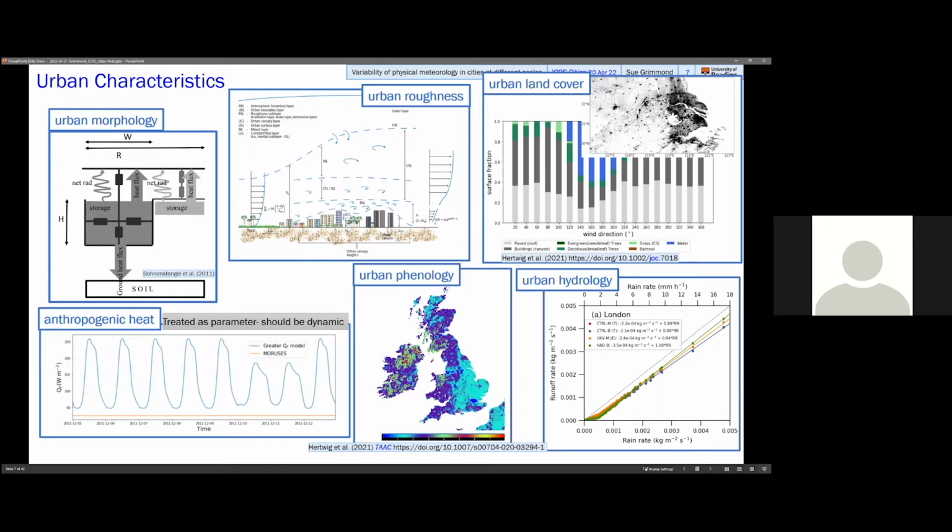We also need to account for the roughness of urban areas. This may be represented by drag coefficients and/or roughness lengths and zero plane displacement heights. These typically assume that the buildings are all of the same height and use models such as the MacDonald functions.